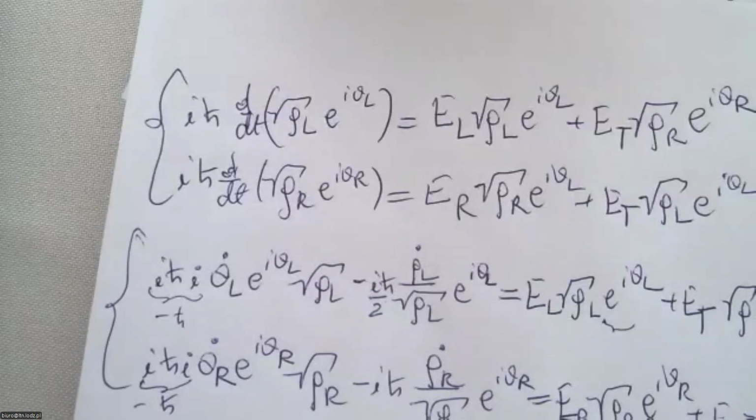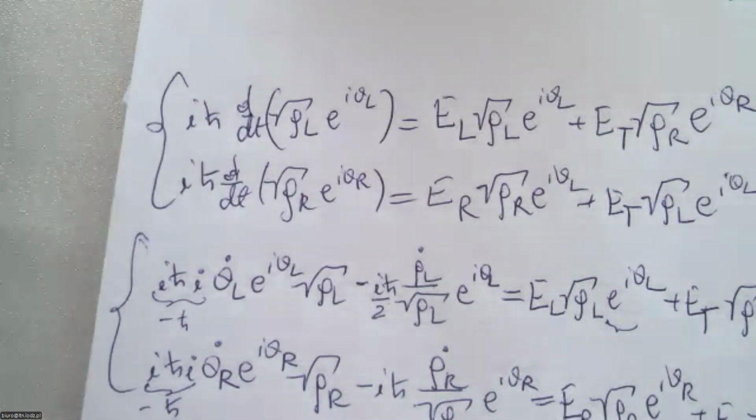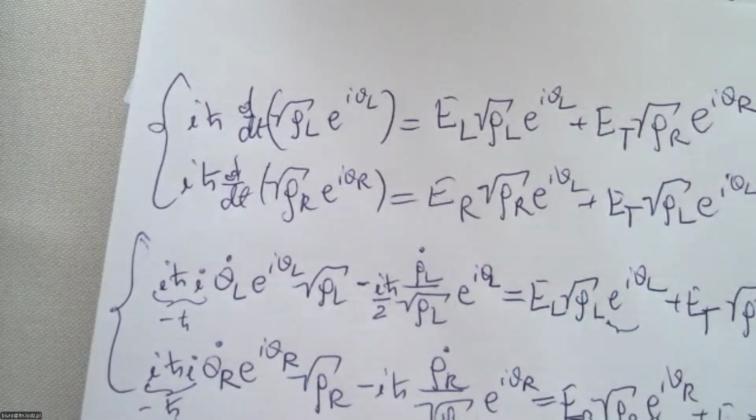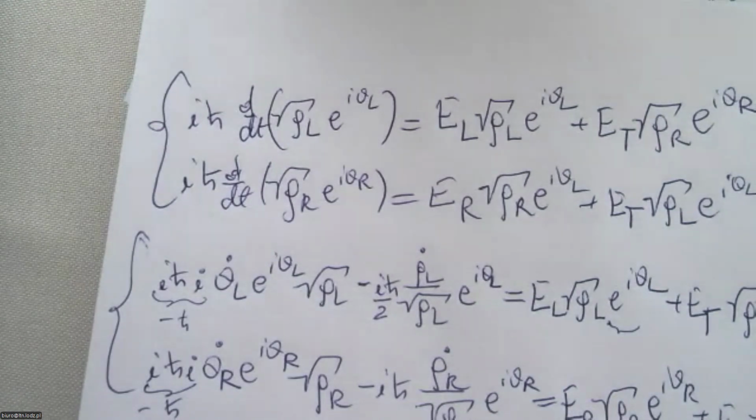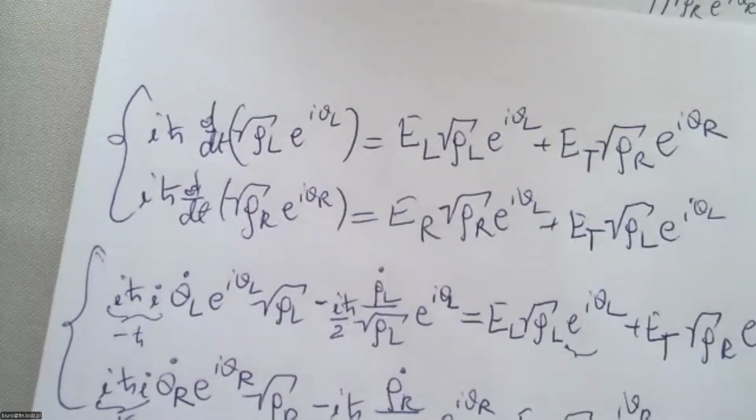Okay, so this is our first equation. I think it's quite understandable what has been done here. And the second equation goes almost immediately with that because, you will see, the mathematical structure of the equations is the same. So this is a system of two coupled ordinary differential equations, right? In the case of rapid single flux quantum electronics, as developed by Professor Hannes Töpfer and Yoshikawa or Fujimaki in Japan, it's sufficient to use this two-fluid model. Nevertheless, we can always go beyond this model because this RCSJ model will generate various families of current-voltage characteristics.